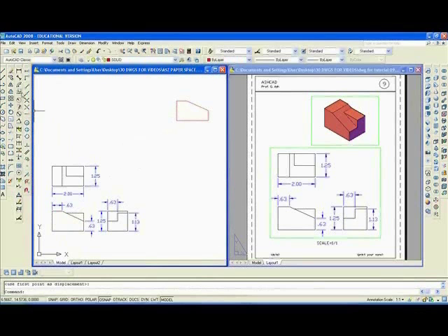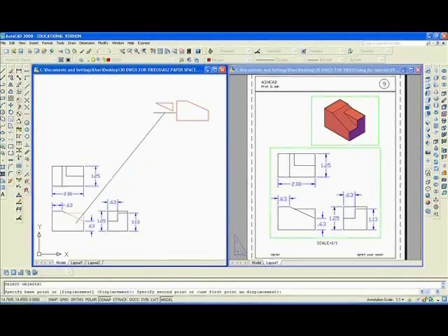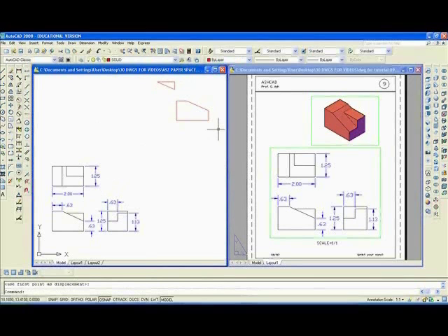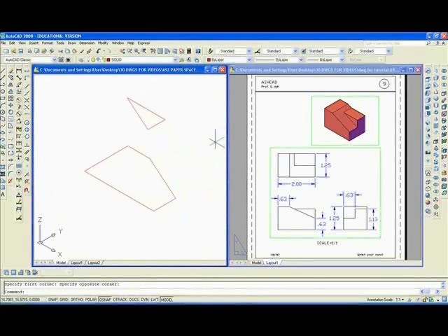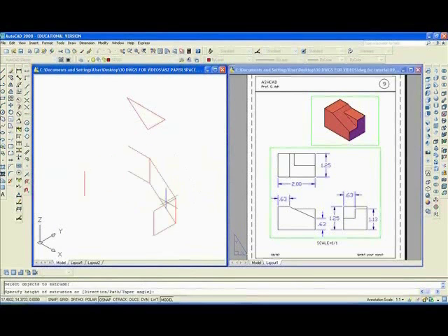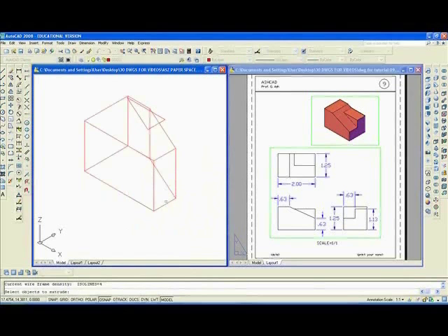Also, you want to do another polyline of that right triangle. M enter, L enter, and move that up as well. Go into southeast isometric and zoom with the window what I'm going to convert into a solid. I'm going to type EXT to extrude the polygon 1.25, enter,